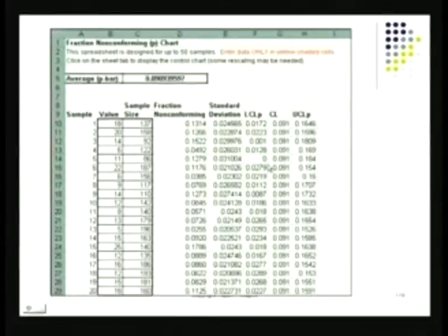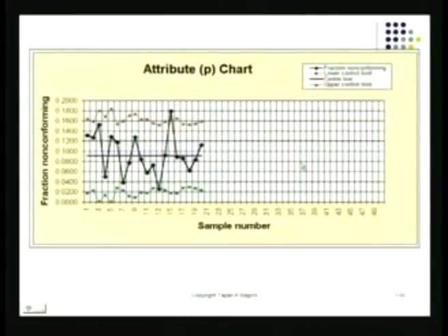I can again focus on troubleshooting. That I'm able to do. So the P chart would really be no sweat at all if you did it this way. And this is also not very difficult at all. And notice here something that I did not show you earlier. Notice the variable width of the control limits. Can you guess why it is this way? Because the control limits of the P chart have this N in the denominator.